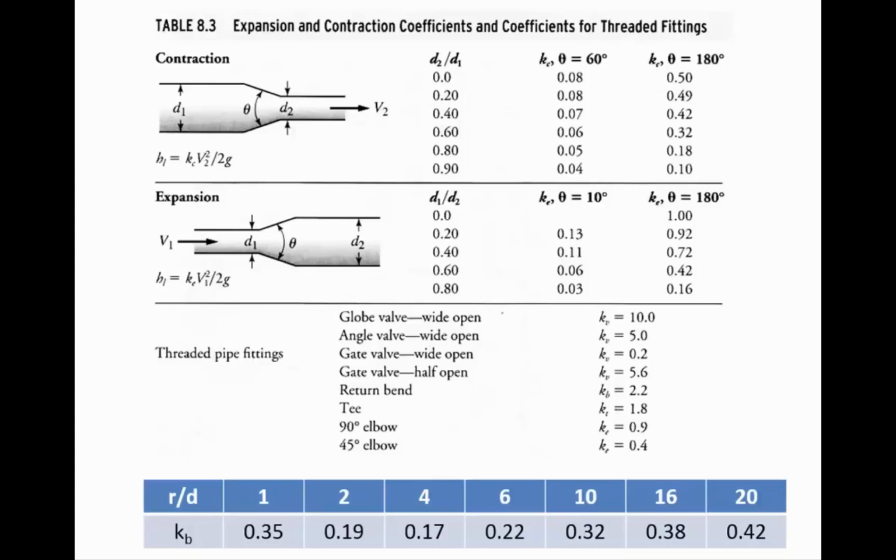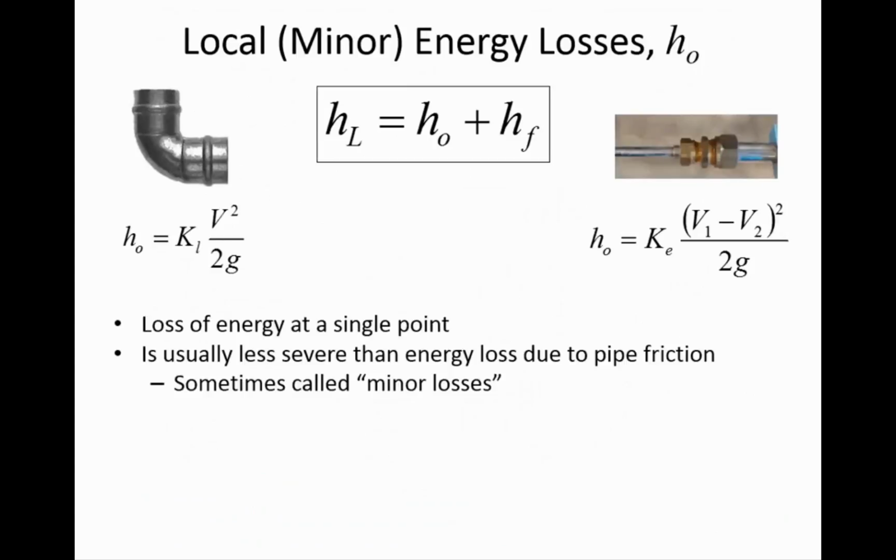We have the case of water coming out of a tank, and what it's showing is if you have an infinitely large orifice and a small pipe, that's like the top row there where it's saying 0.5. So what they're saying is that when you have water coming in from a tank to a pipe, then the K value is 0.5, and you take that K value and multiply it by the velocity head, v squared divided by 2g. So whatever the velocity is through the pipe, even as the water is going into that pipe, it would be 0.5 times v squared divided by 2g.